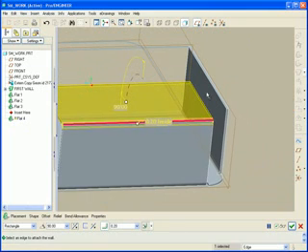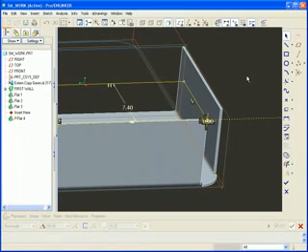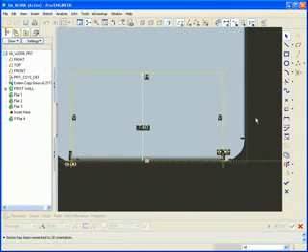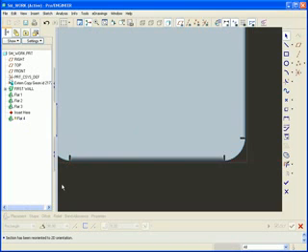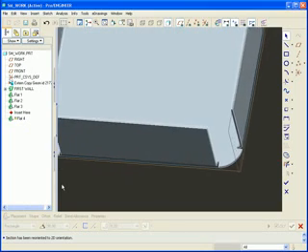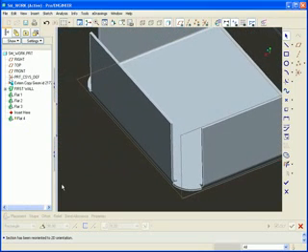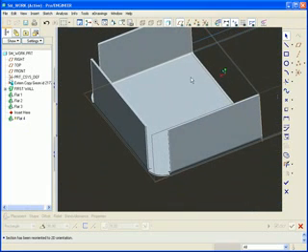Now this wall needs to have a very specific shape too, so we'll go straight into its sketch, and in this case I'm just going to box everything and delete it all, and take advantage of the fact that we've already got quite a bit of geometry on the bottom. Now, when we create a wall and we pick an edge to attach to, the edges of the sketch must connect to those edges, that vertex.